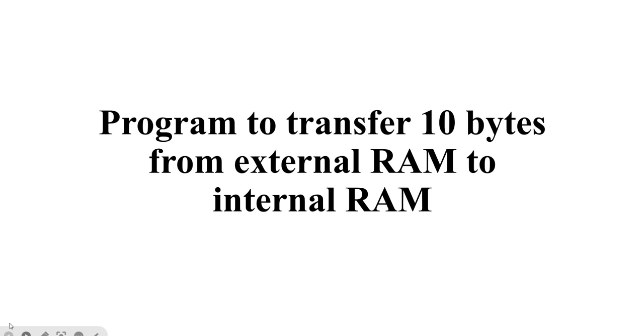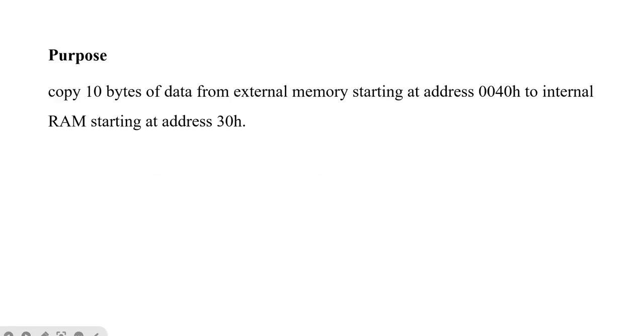Mirajkar, and today we will see an 8051 program to transfer 10 bytes of data from external RAM to the internal RAM. Here the purpose of the program is to copy 10 bytes of data from the external memory starting at an address 0040H to internal RAM starting at address 30H.